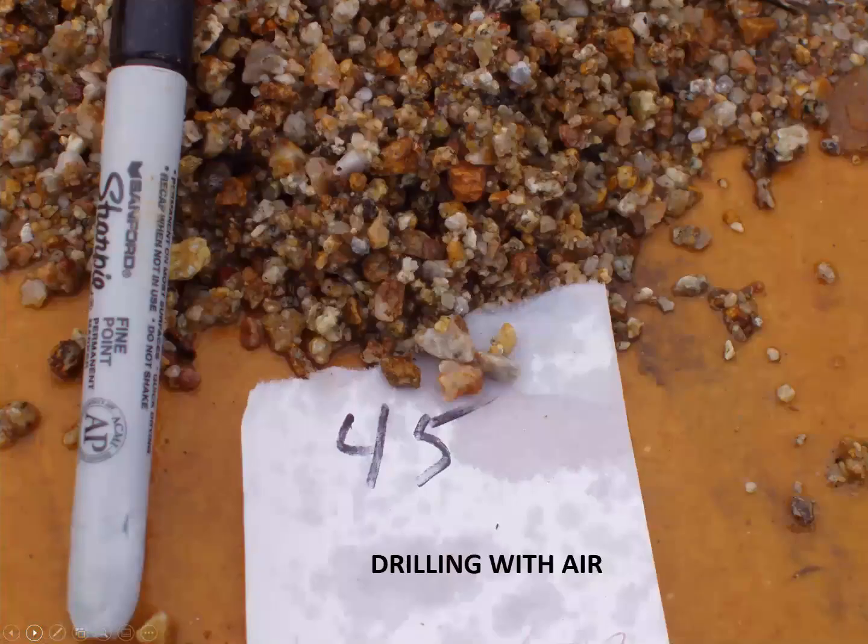So this is what one of the aquifer materials looks like when we're drilling with air. This is pretty coarse. This is at the upper end of sand size, or maybe very fine pebble size, but this is a very good aquifer material. You could really push water through this pretty well.